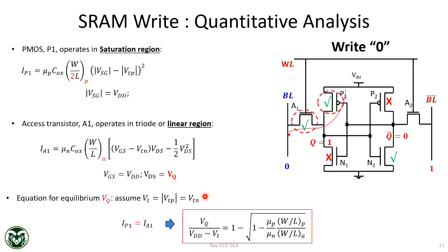Yes, you may be right that if the metastability point in your butterfly diagram is 0.5, write can take place, but there is only a chance. Sometimes it may take place, sometimes it will not. But if you set it to the threshold voltage of the transistor, write will definitely take place. That's why a good SRAM designer will set VQ at least to VT.